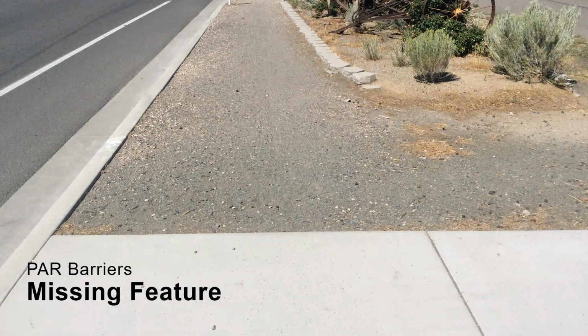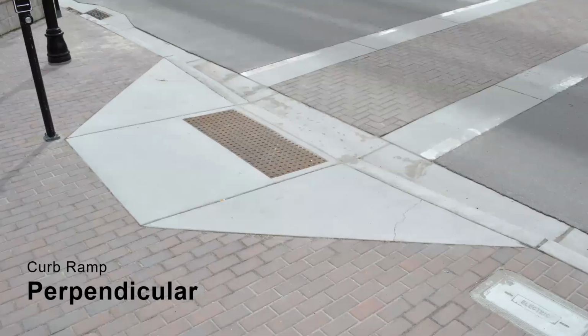The public right-of-way also must include accessible features, such as curb ramps, which provide a transition from the sidewalk to the street level. Nearly 80 attributes may be collected for a single curb ramp using the Public Rights-of-Way assessment process, which follows both ADA standards and the Public Rights-of-Way Accessibility Guidelines, or PROWAG. These many attributes are narrowed down to the most essential characteristics for accessible curb ramps in our app sidewalk assessment process. Ramp slope, landing slope, ramp and landing dimensions, detectable warning surface design, gutter slope, and more are collected to evaluate the safety and compliance of each curb ramp installed along the public right-of-way.